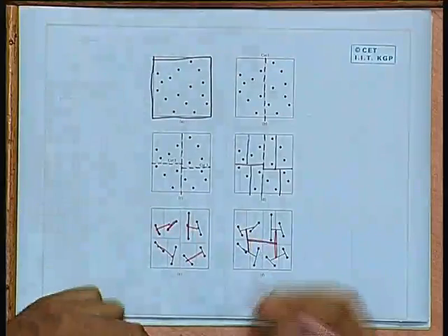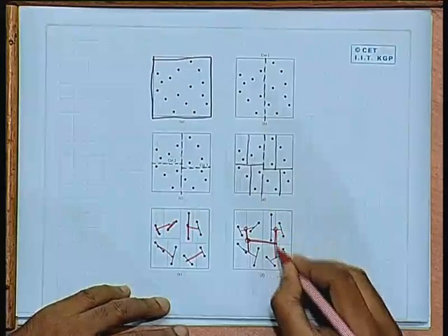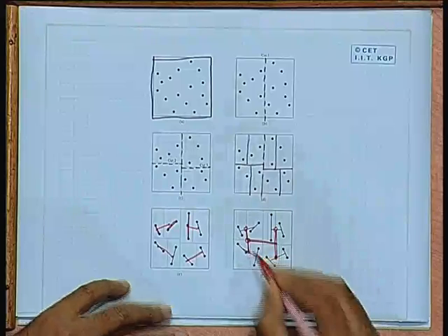Clock skew will be there, but you are trying to minimize it. Here you are not making an exact estimate and trying to make it equal. Each junction of this will have a buffer, there will be a buffer inserted in each of these junctions.